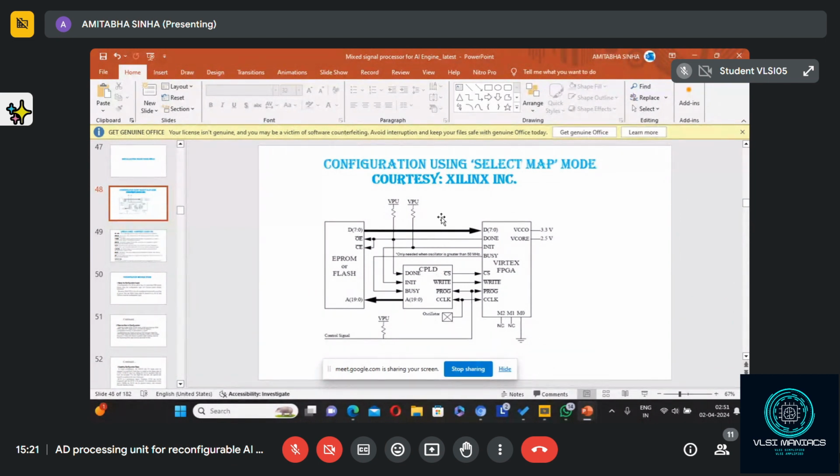Normally in your laboratory, these FPGA boards will be connected to your PC through a USB port. But normally for the design, if it is a complete self-sufficient board, then the CPLD through a parallel bus will be connected to the CPU. That's all. And one line will be connected to the interrupt line of the CPU.